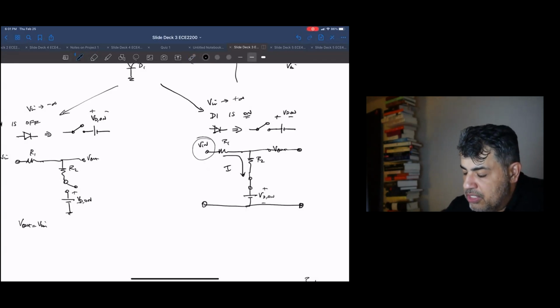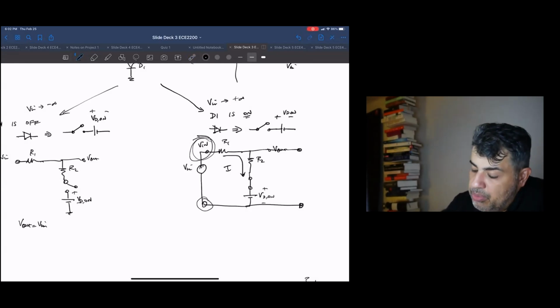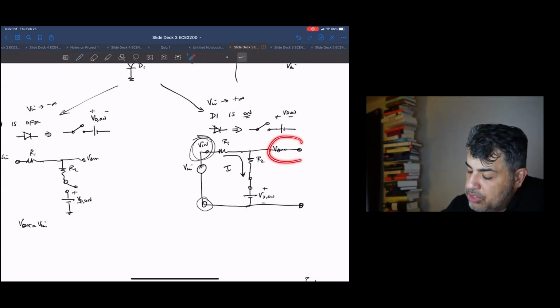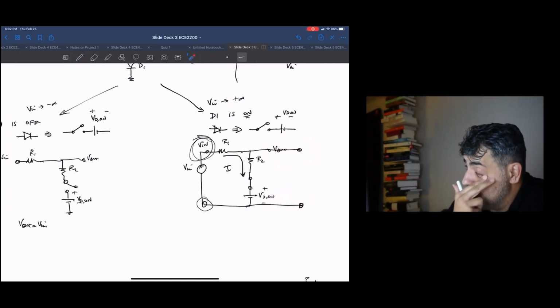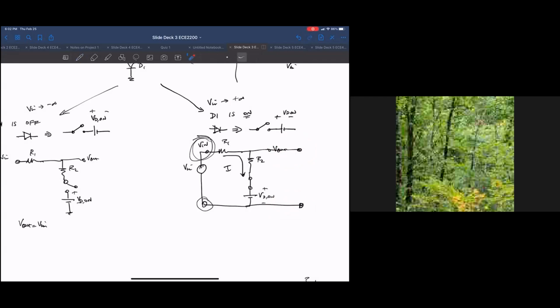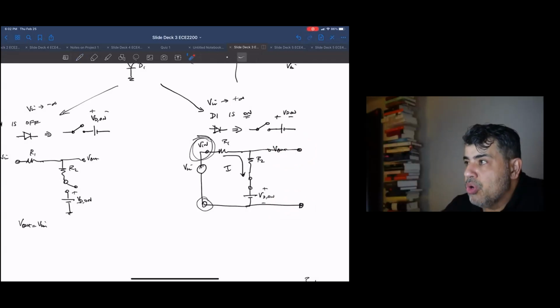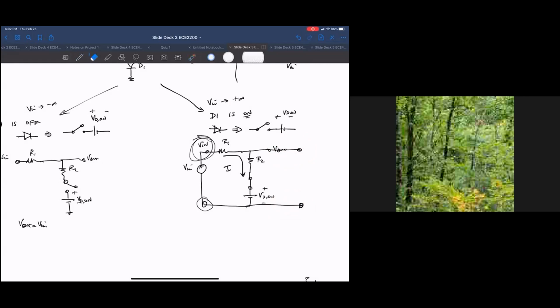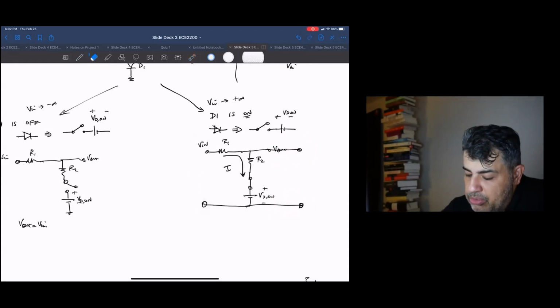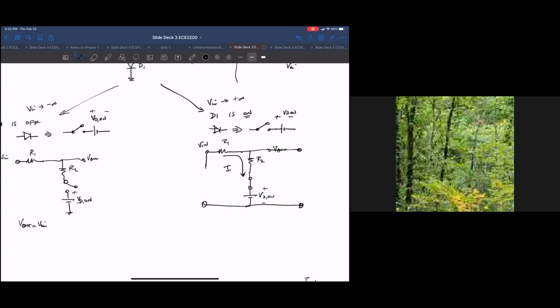So you could say Vn is the voltage difference between this point and this point, or you could draw an actual voltage source here if you want. But then you have this sensing node, where you're sensing that voltage, so it's also the voltage drop between this point and this point. Is there something else on V out, or is it just floating? It'll be your multimeter or something. Okay, I see. So if I was going to draw how it really looks in real life, you would put a battery or voltage source here.